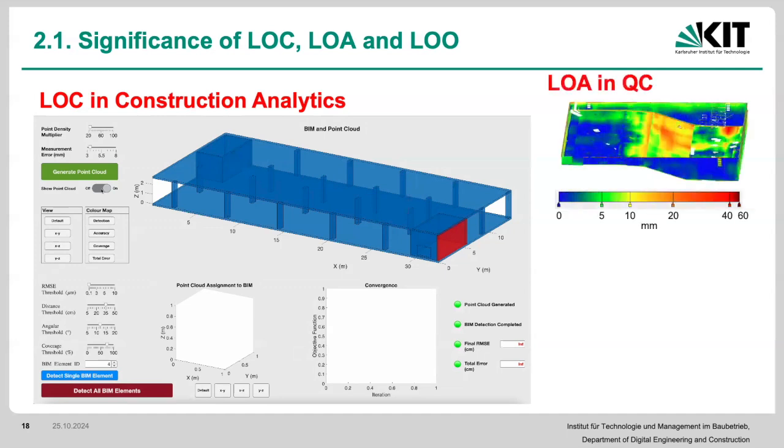The other one is level of accuracy. Well, here I have 5 millimeters, 10 millimeters. I mean, these are a bit high, but let's say if these were 6 millimeters, 4 millimeters, 2 millimeters, instead of an order of magnitude less, the accuracy there. I can only make that decision if the point cloud is collected in a way that could justify the amount of precision that I'm expecting of it at the end of it. If it's not, then we cannot have it as a basis.